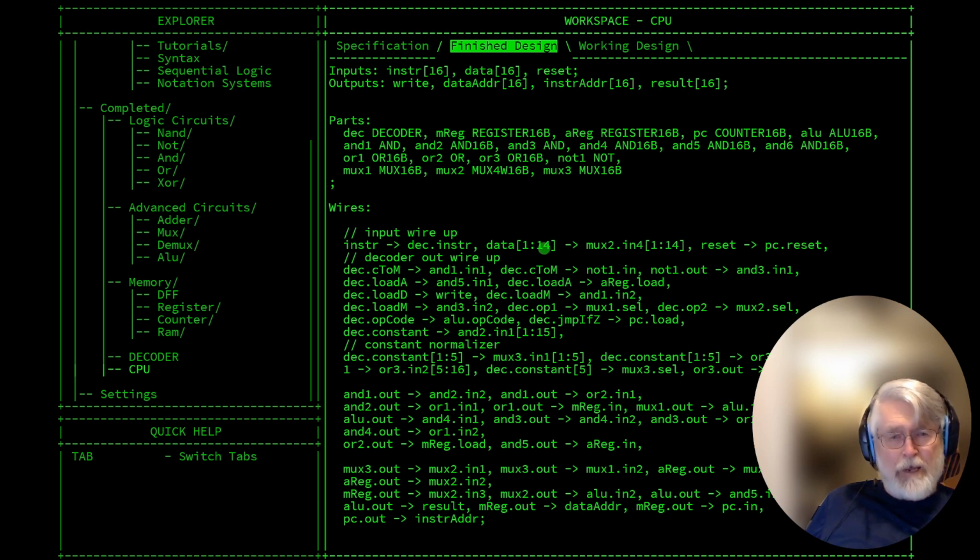But if you ever depend upon the 15th and 16th bit within the data input, then the outcome is not going to occur. Apparently, the testing that they did for this logic did not include any data that had a higher number than what would fit within these 14 pins. So it went ahead and passed it, even though it really is not a valid design.